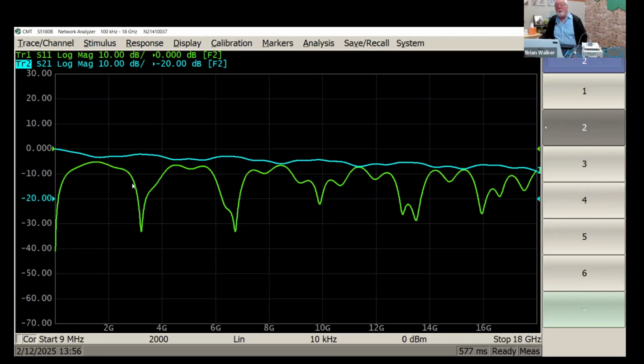This is terrible return loss. I mean, this is minus, what is this, minus 5, minus 7, and the insertion loss is suffering as well. So that 25 ohm section is doing some real damage to the response of the transmission line, as you would expect. And the time domain allowed us to find exactly where the problem was. Now, I could actually look at it and see, but sometimes these problems are a lot more subtle, and the time domain analysis will really bring this out for us.